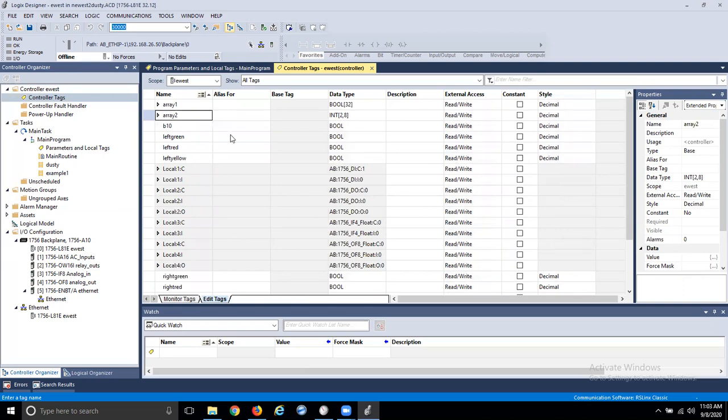So this is a 1 point. You made it a Boolean. For a stoplight, left green, left red, left yellow. These are just Boolean points. They're going to be points in memory. So instead of having an address picker and going in and labeling what everything is, you start with a label, and then you tell it the data type, and then the software sort of keeps track of it.